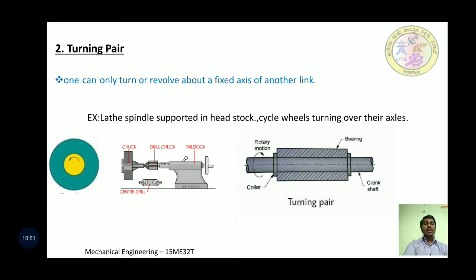So I will briefly explain what is a lathe chuck and what is a lathe machine. Lathe chucks are used to accurately clamp a workpiece on a lathe for different operations. It may be turning operation, facing operation, thread cutting operation, knurling operation. There are different types of chucks, but 3-jaw chuck and 4-jaw chuck are commonly used. So we studied about lathe chuck. Then what is a lathe?